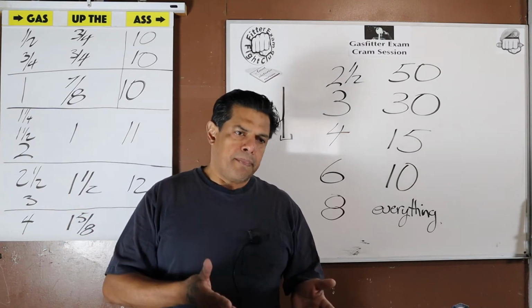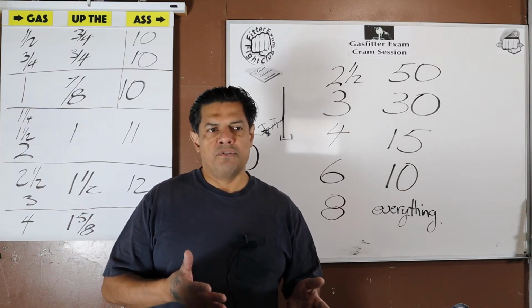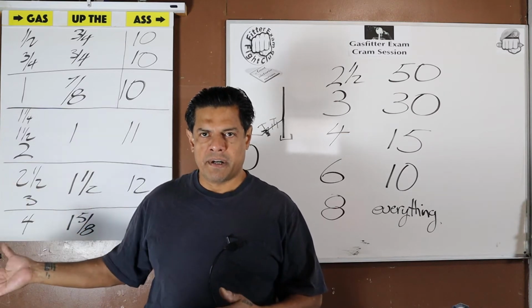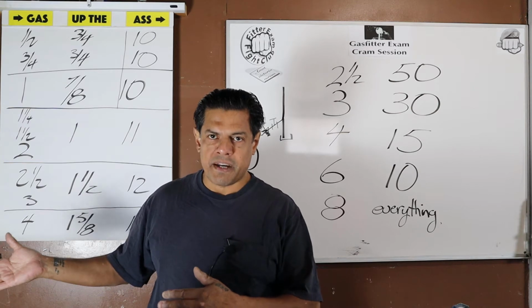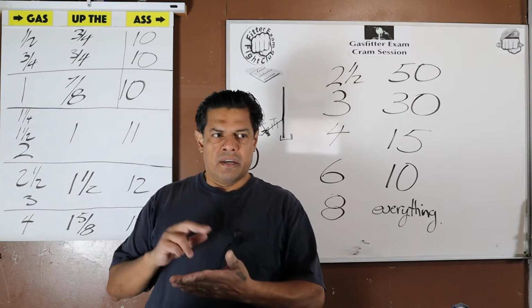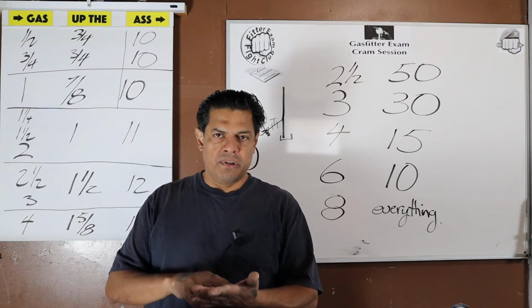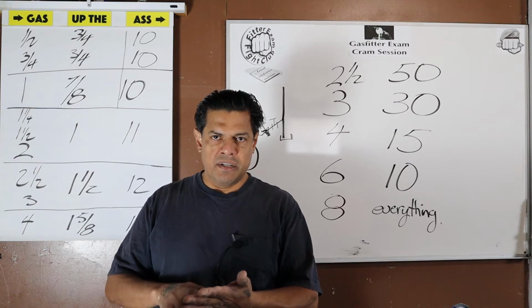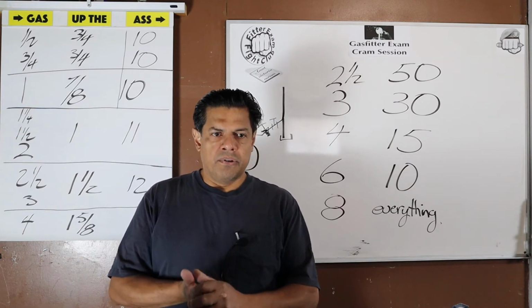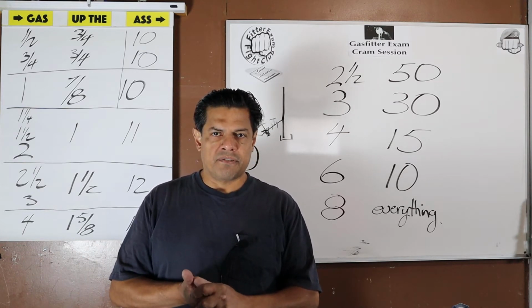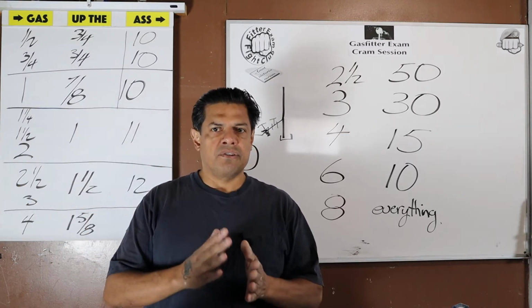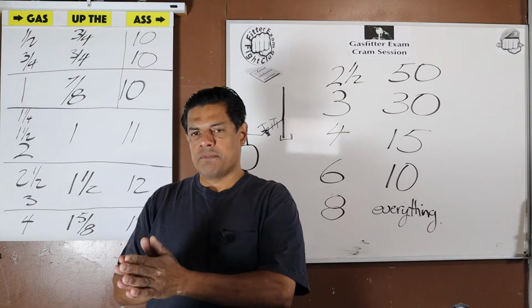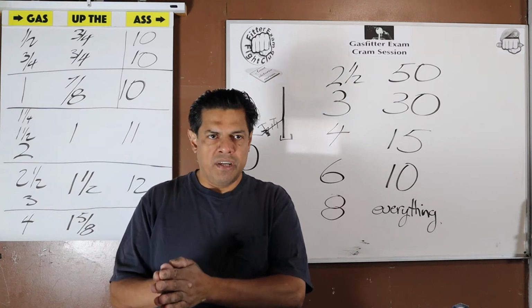So, in certain situations, you might want to check the nameplate on the unit, the manufacturer's plate, giving you the stats of the unit, how much gas that unit needs. Or, you could check the manufacturer's information that comes with the unit. That's going to determine what size pipe you're going to need, what demand you're going to need.